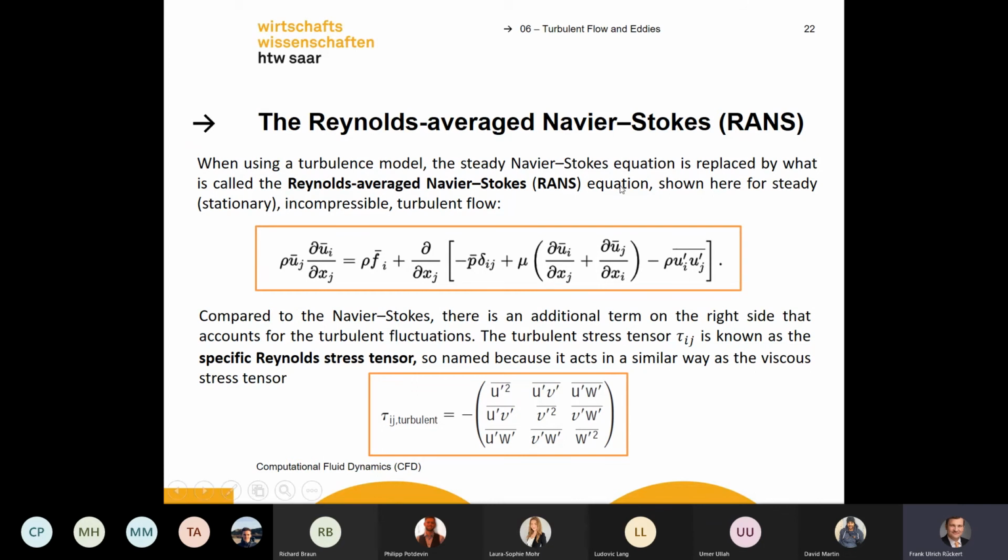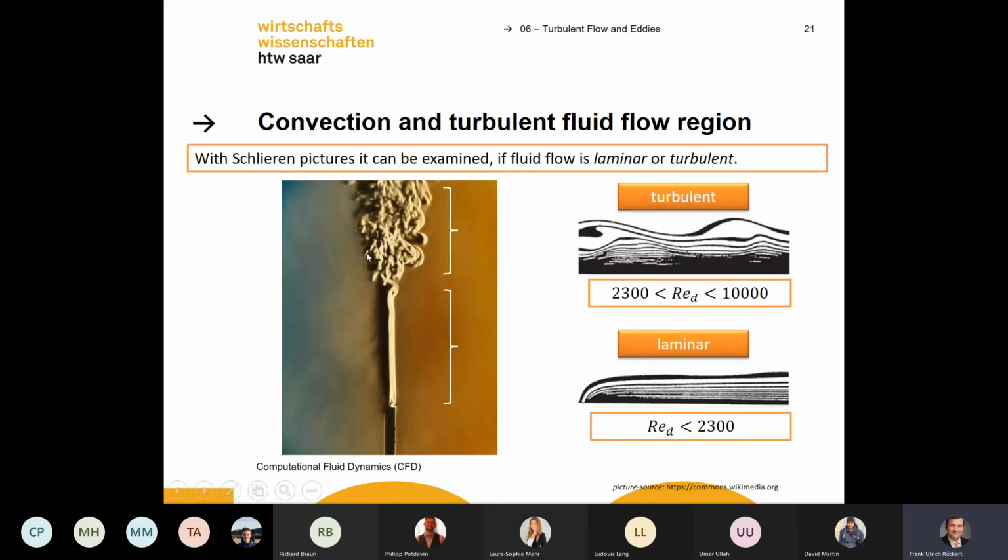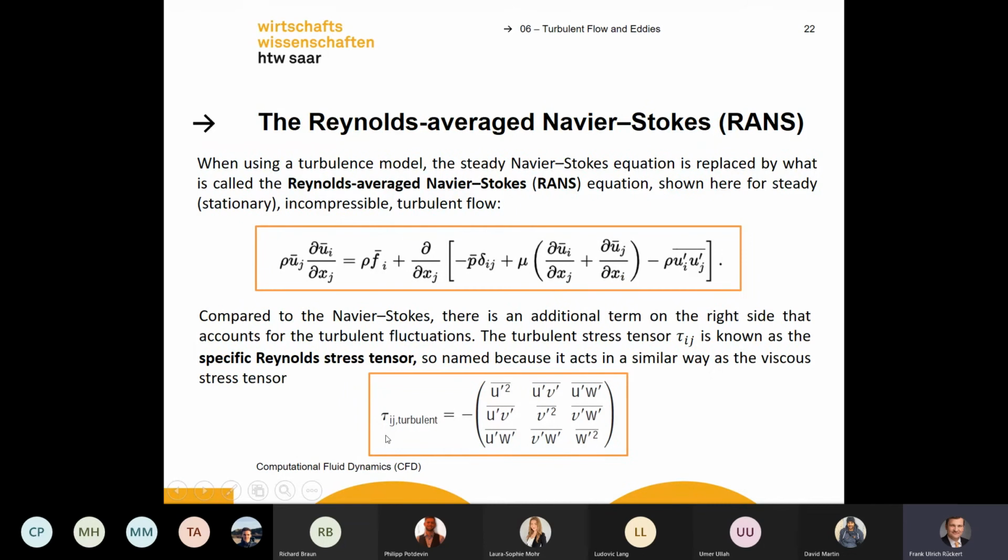And if you look back at this picture, you can imagine this is pretty difficult. If you make a mesh here and want to describe it, it's really complicated. And so it is also in this formulation. You need a so-called Reynolds stress tensor, tau, and you have to calculate all the fluctuations and derivatives in a matrix for every cell. This is included in this turbulence description.